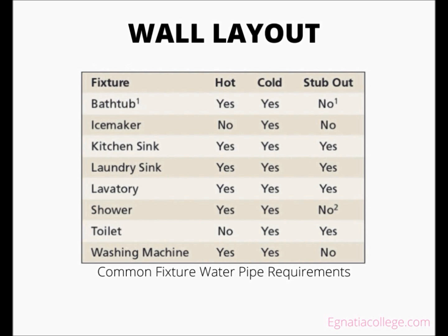A sink installed in a countertop offers more flexibility as to where a pipe terminates than does a stub-out serving an exposed fixture connection. Because water flows through the piping system under pressure, the piping can be routed in any position to accommodate specific job conditions.